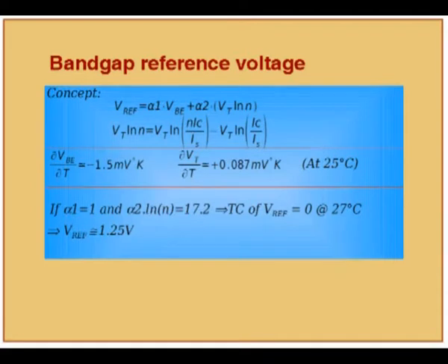And the next thing is that here I don't have anything specific which will affect the value of the reference voltage. We will show that it won't be a function of process parameters. It will be a function of silicon band gap. But silicon band gap doesn't change as such, right? It changes with temperature, but it changes very slowly with the temperature. So it is a good candidate for generating a fixed and stable reference for the entire circuit. So we use the silicon band gap voltage to generate this. And why this silicon band gap? It can be explained.